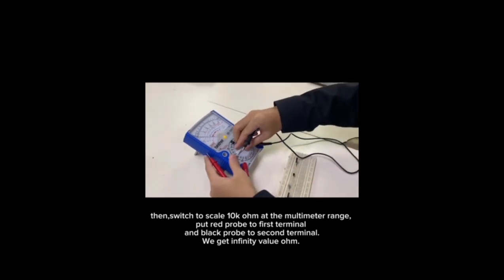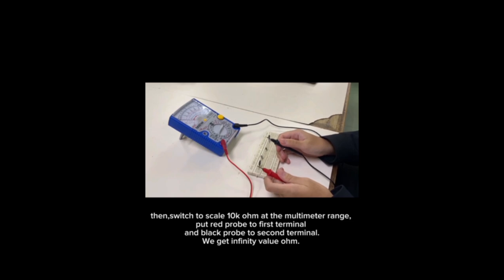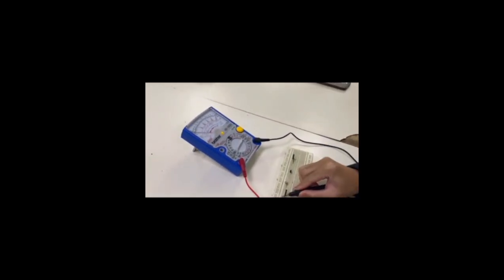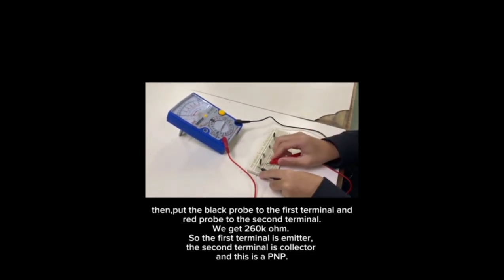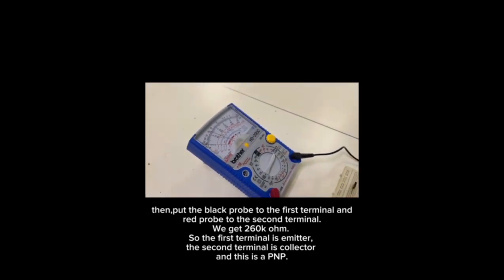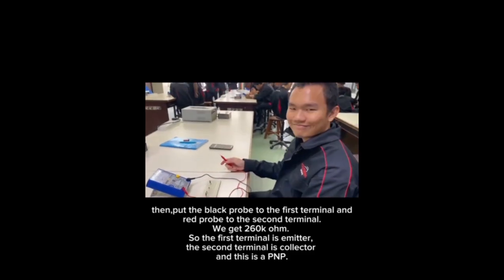Switch to the 10 kilo ohm scale on the multimeter range. Put the red probe to the first terminal and the black probe to the second terminal. We get an infinity value of ohm. Put the black probe to the first terminal and the red probe to the second terminal. We get 260 kilo ohm. So the first terminal is the emitter, the second terminal is the collector, and this is a PNP.